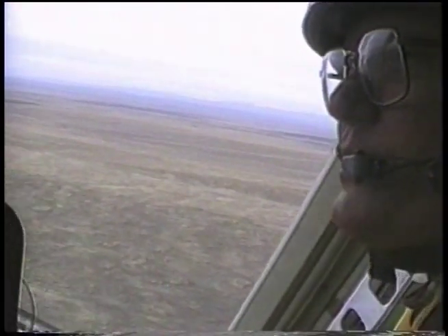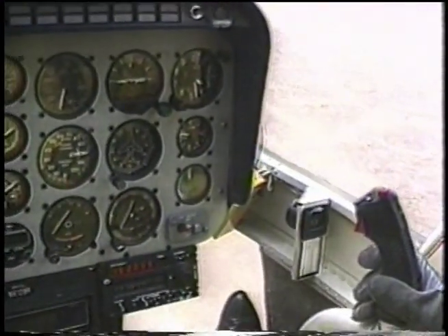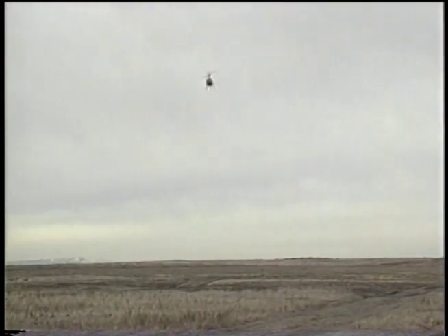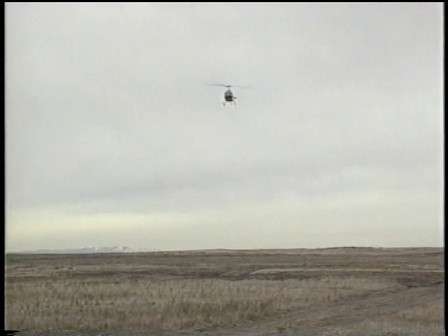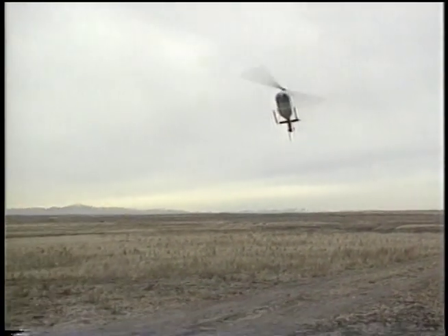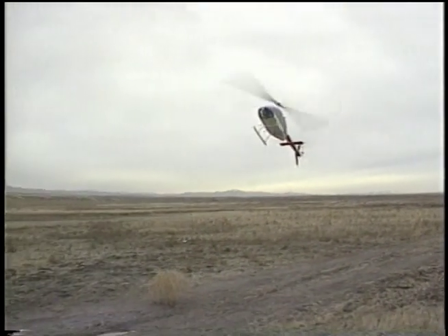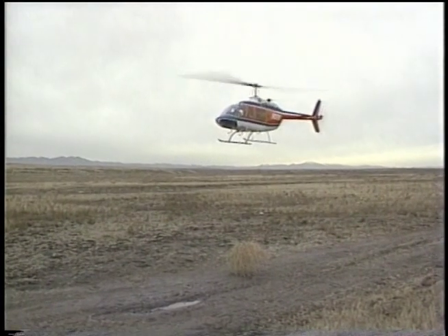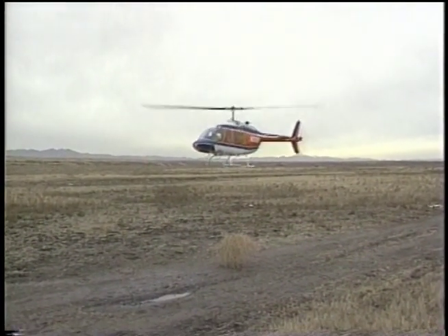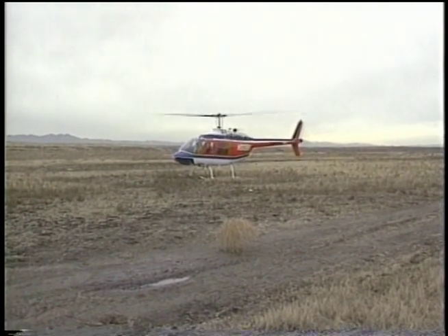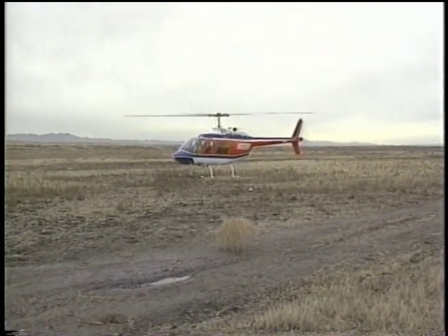The pilot has full control of the helicopter during this maneuver, as I will now demonstrate for you in this practice auto-rotation. Here I have completely lowered the collective and removed all power to the rotor system. The helicopter descends rapidly at this point. As I approach the landing site, I ease back on the cyclic, raise the helicopter's nose, and slow the forward airspeed and rate of descent. Now, I level the helicopter, and using the stored up inertia in the rotor blades, I cushion it to the ground, completing the auto-rotation.